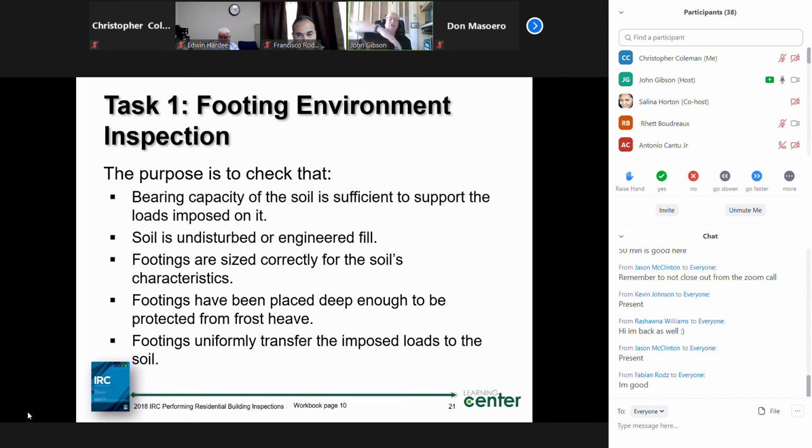So let's take a real steep hillside, and I have what is partly in the ground, or maybe it has ground up to it, but yet there's a point where I go from the first floor and I measure down the side of the building, and we've got finished ground 12 feet or lower, that's where my exposed wall is for that basement area. Then they're going to say that basement gets considered a story above ground too. So those were the two conditions which dictate that it's going to be a story above grade plane.